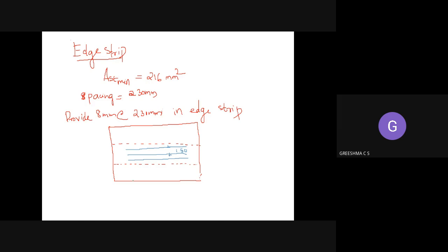In addition, we have provided reinforcement along the edge strip. In the edge strip, here also we have provided 8 mm diameter bars at a spacing of 230 mm.